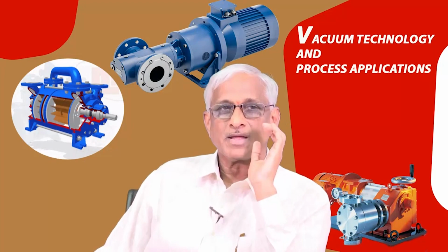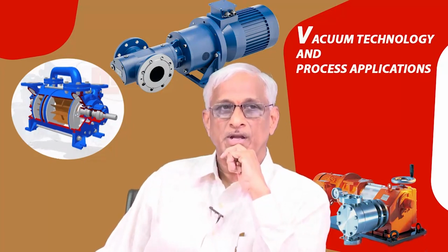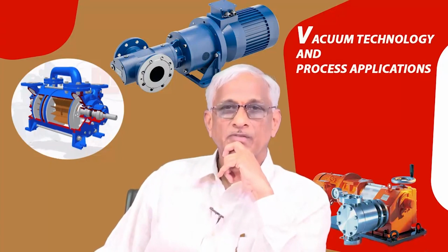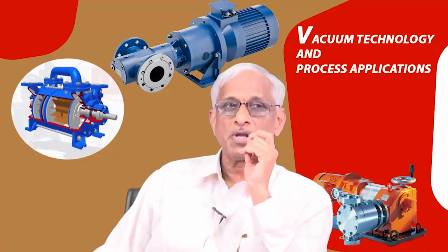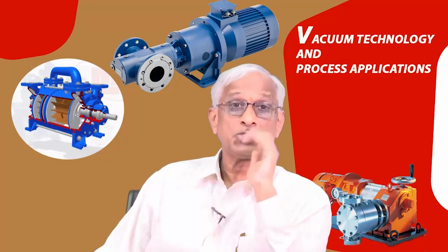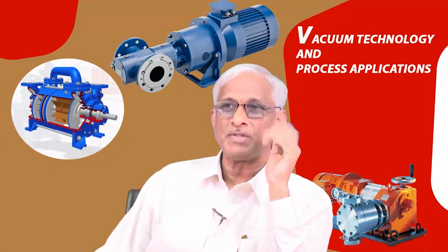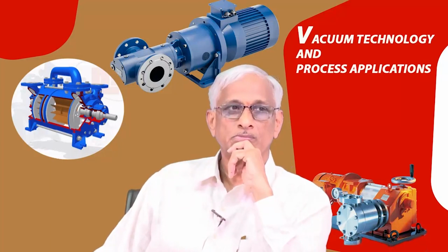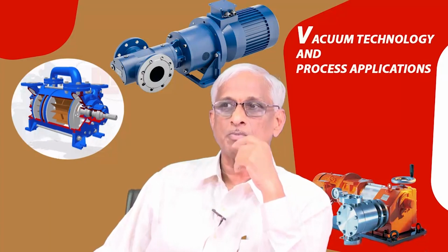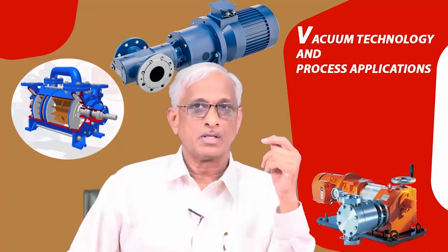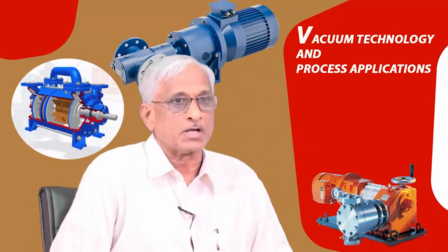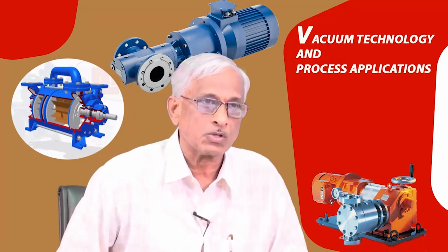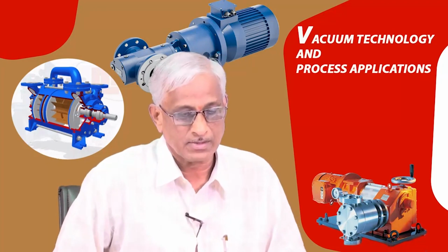So, there are special features associated with the liquid ring pump. In addition to evacuation, it can handle wet loads, it can handle particulate loads also, which a rotary pump cannot handle. If there is dust coming inside, then immediately the rotary pump gets into trouble. Some chemical vapors coming into the pump, you are in trouble. Whereas the water ring pump can handle some sort of chemical vapors. It also can handle particulates, etc.